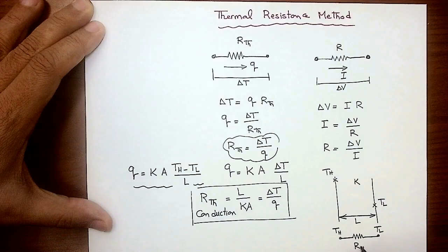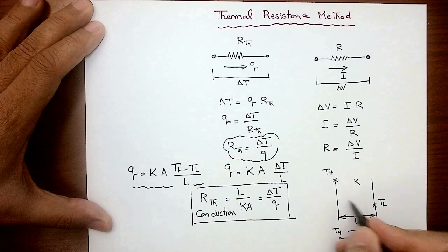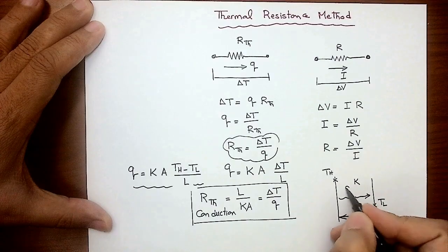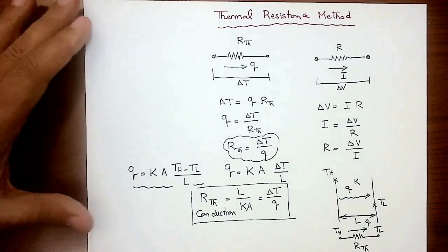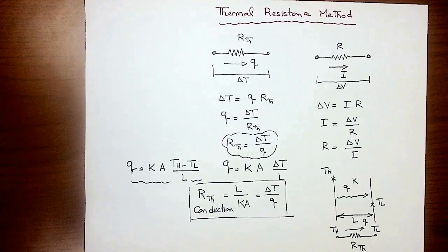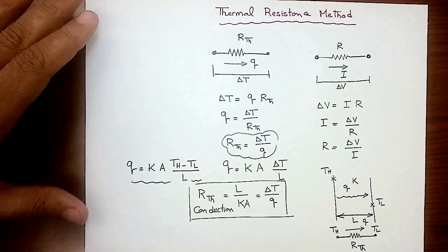And this is a thermal resistance that can be calculated from thickness L divided by K times A, where A is the area going into that page here. And what's moving inside that resistance is actually the heat transfer Q, which is driven from the hot wall to the cold wall. So I did simplify a single wall conduction by a single resistance. Okay? So now, if I go back to a problem